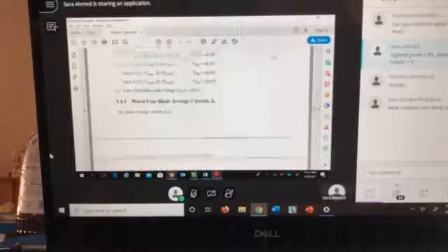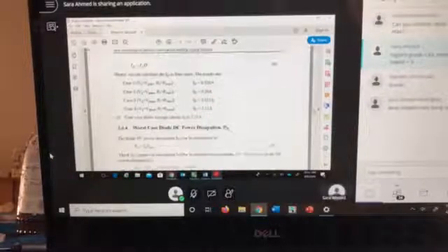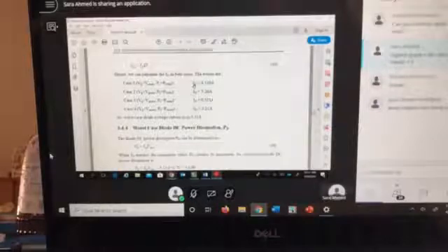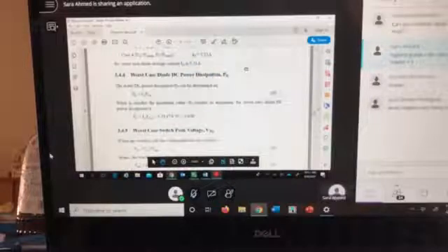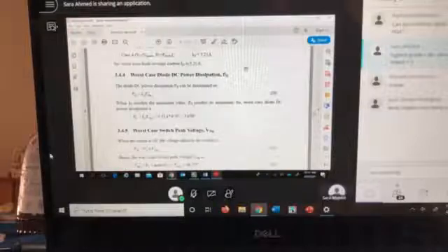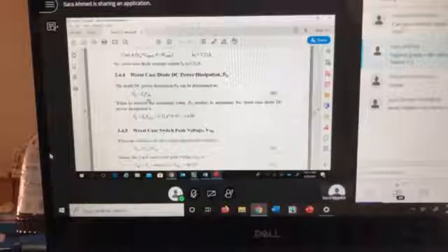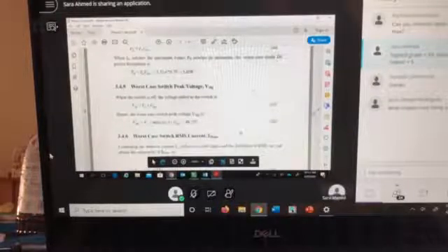So we got the voltage across the diode, the current across the diode, and we again calculated for the 4 cases of your I of L. So you have your I out, 4 cases, and then the power loss for the diode is PD equal to I of D times the voltage. You have 2 equations for the power: either P is equal to V times I, or P is equal to I squared R. Here the power is equal to V times I because we calculated the voltage across the diode and the current across the diode. So you multiply them together and you get your loss, which for this case was about 3.65 for the diode. Then after that, we want to do the same thing for the MOSFET.